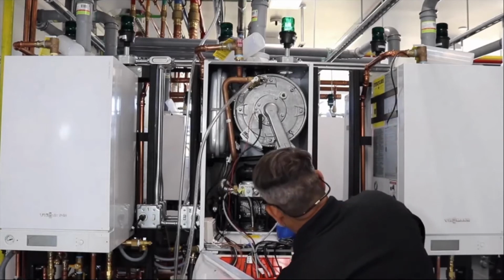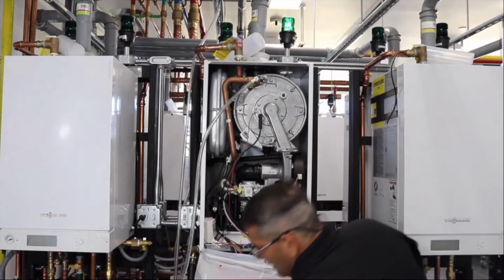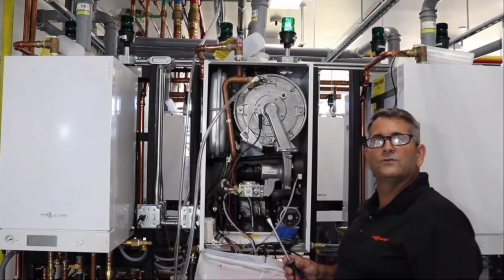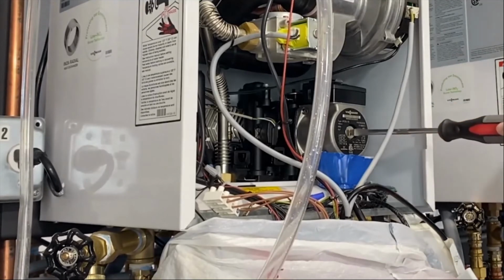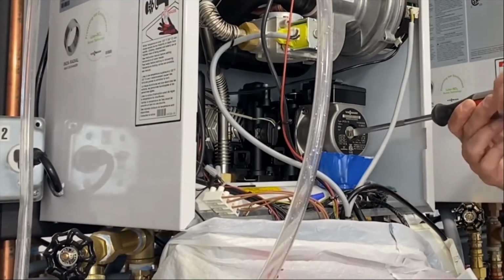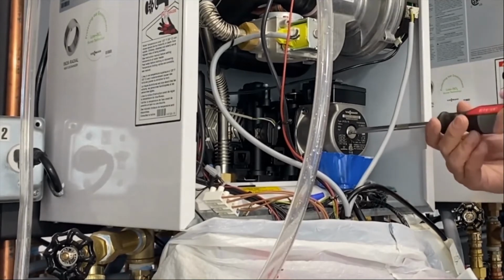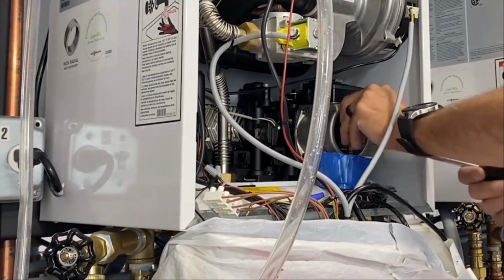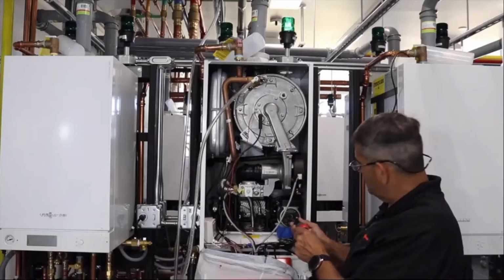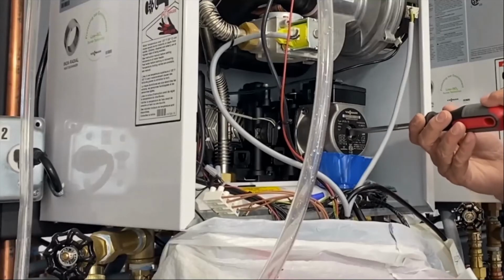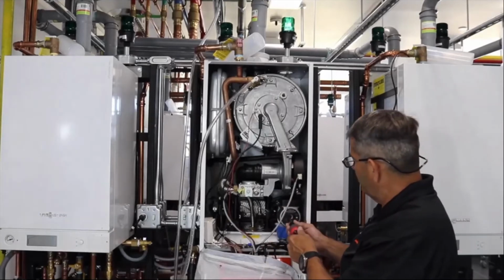So the next thing we want to check is to see if our pump is turning. And with that, you're going to need a larger screwdriver, like a 5/8 screwdriver here. And right here, a lot of people don't know, but when you first install this boiler, they ask you to take this cap and bleed the pump. Make sure that you're getting all your air out of your pump. Then when you look inside there, there's actually a shaft to hold your screwdriver. It could be a slotted screwdriver, or sometimes it's a torque wrench, depending on the pump itself.